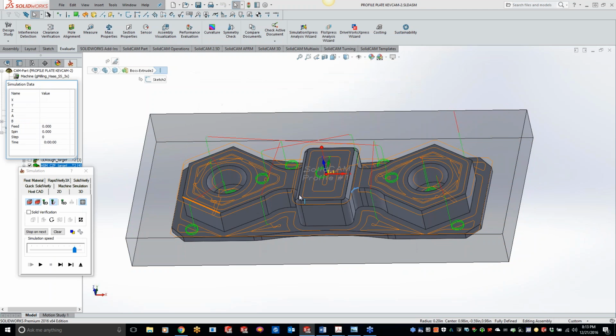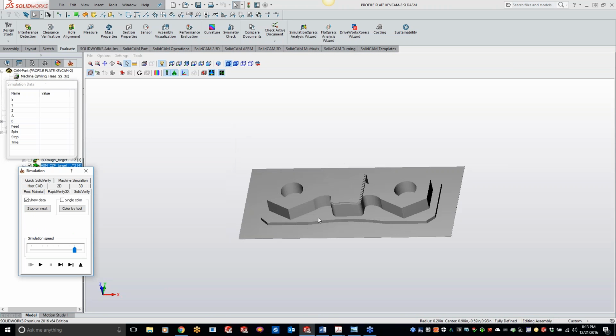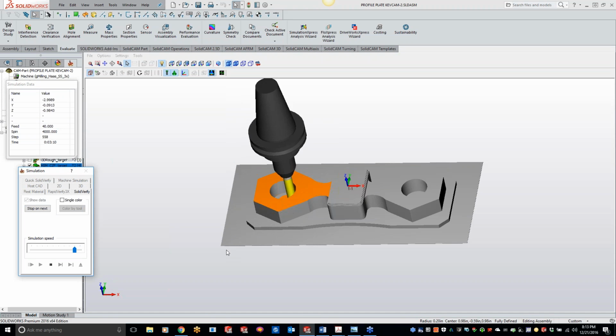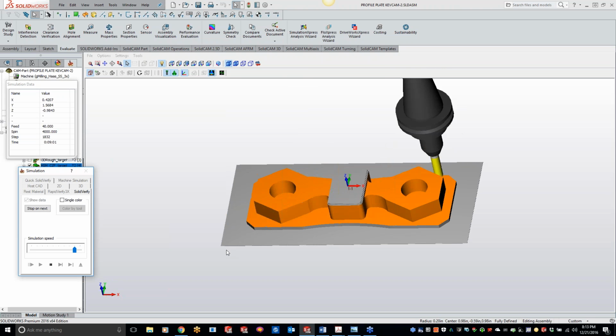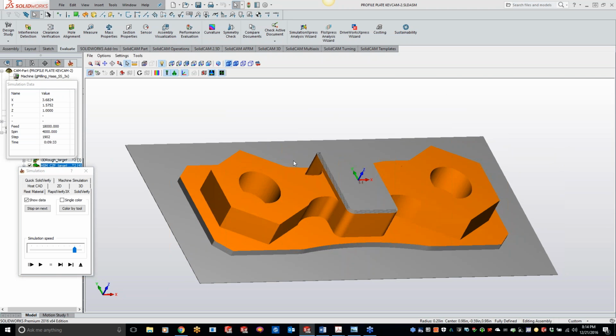And now, you'll see we got a nice tool path going in there, basically like a contour pocket style. You're going to have a really nice finish on all these areas. If I zoom in just on this top piece right here, it's basically doing a step over, doing a nice flowing line so we're not getting any jerkiness, so you won't have any little polish marks when it just does a straight jump over. If we do a solid verify here, we get that nice pretty finish going all the way around. Any questions so far on what I've just covered?